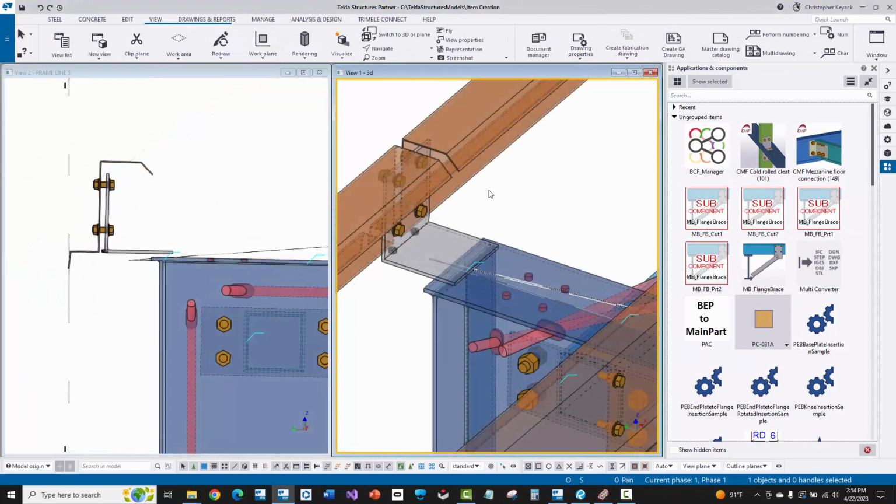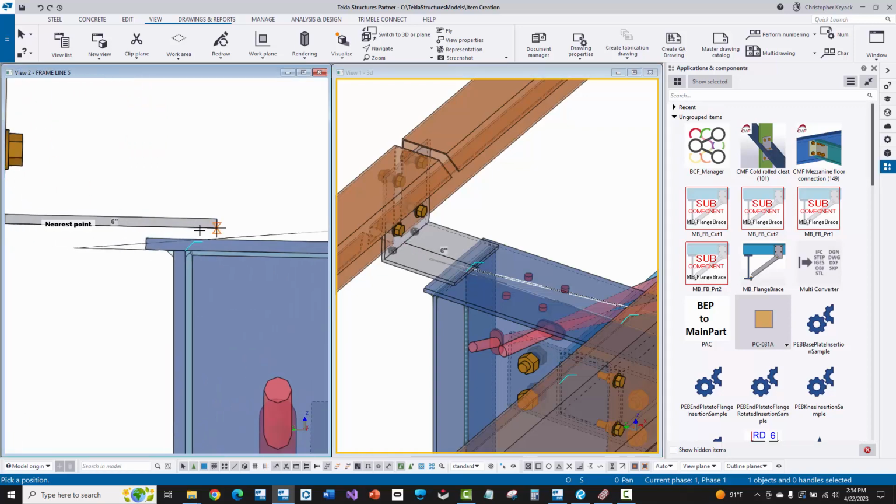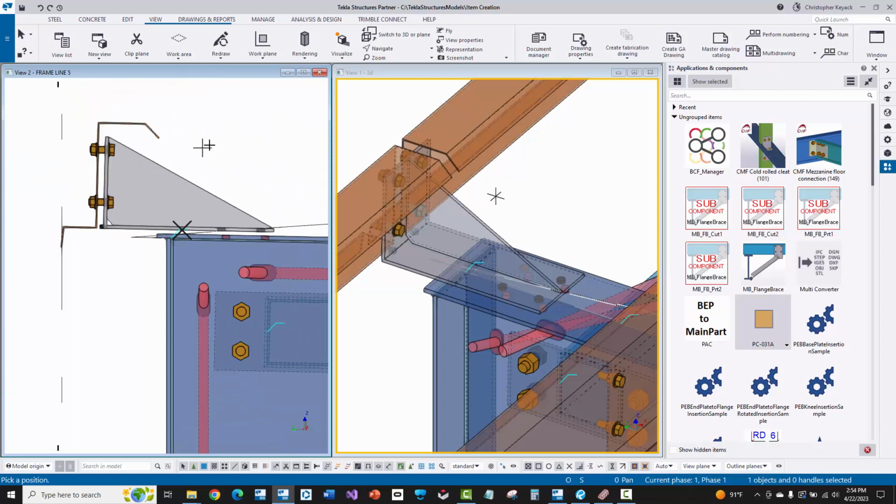Okay, so now I'm going to actually show this in application. This is actually for a metal building, and I imported this in from MBS, and the connection didn't quite come across the way I wanted. So I'm going to use the actual original clip that comes from the software as a picking point to put my new component in there. So I'll come in here to my elevation view, I will pick the corner, and you'll see that this is sloping, and so I'm just picking these 2 points along the bottom to get my clip in there that I want.